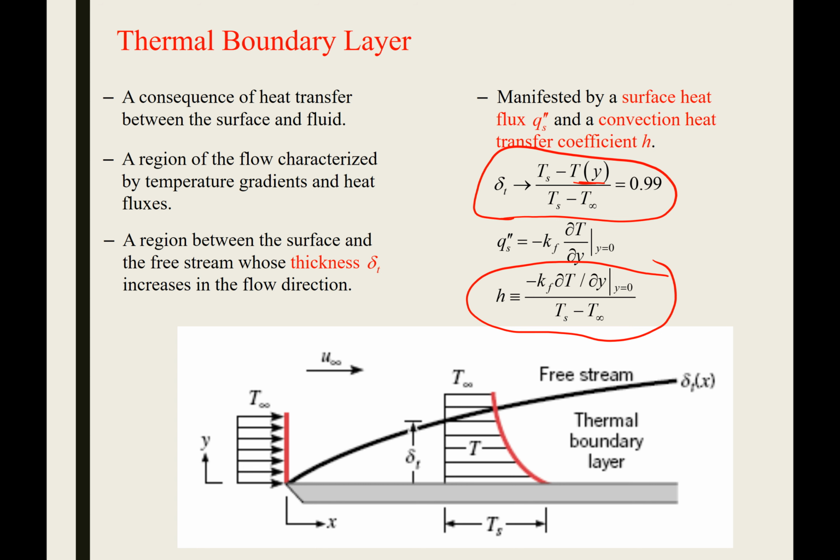I wouldn't worry too much about this. But when a fluid is circulating, you would still expect a fluid with a higher thermal conductivity to have a higher convection coefficient than a fluid with a lower thermal conductivity. Those kinds of fluid properties will greatly influence the value of the convective heat transfer coefficient.